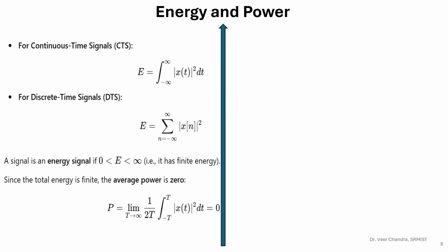And energy and power signals. Now let's find, first of all, how to find the energy of any signal? So integrate over minus infinity to infinity, and take the square, right? X of t magnitude squared into dt, right? So integration of x of t magnitude squared dt from minus infinity to infinity. This is the energy. And power is that you have to divide by the average, that is 1 by 2T, T is your time period.